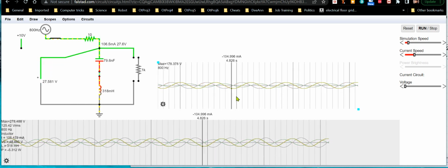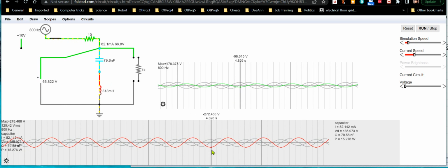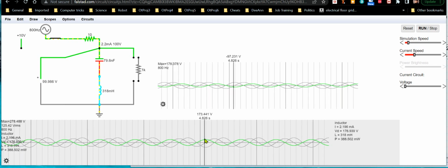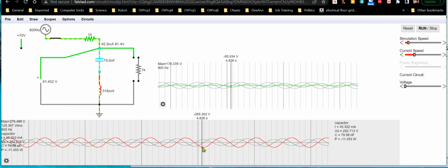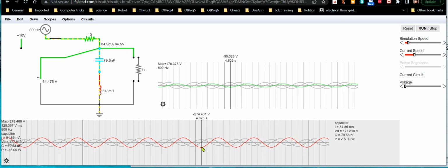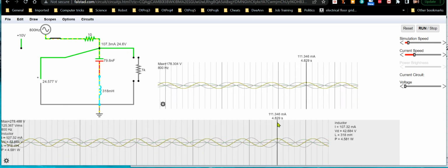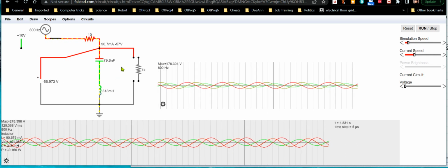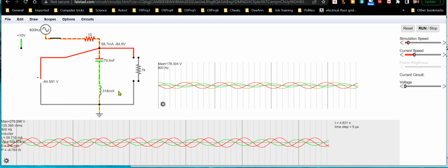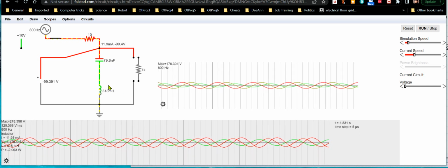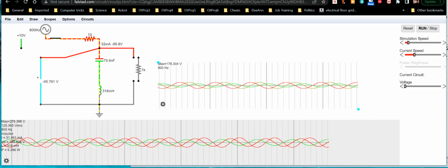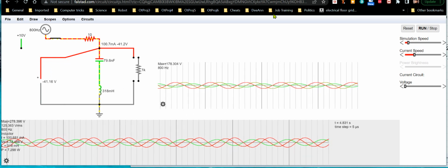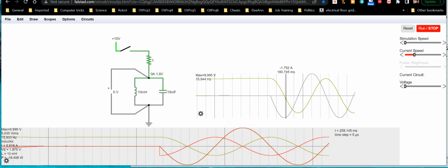As you approach resonance, that voltage gets much more severe, but they're not necessarily identical. Say one's at 270 volts and the other's at 170. They're not the same level, but they're both still pretty high voltages. The capacitive values are different, but that's the only way you can make a resonant circuit: you're looking for the reactances to be equal, which doesn't mean the capacitor and inductor have the same value, like we're dealing with on this tank circuit.